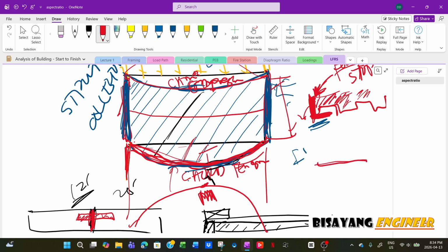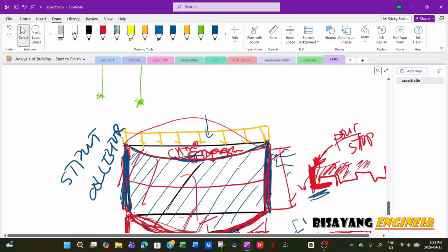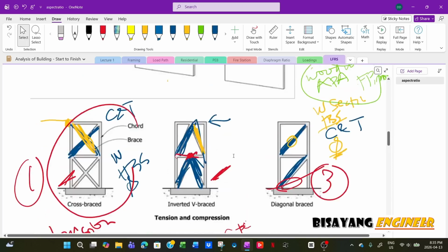So if you have a steel W section, and you are doing, say, a moment plate, like a splice plate right here at the top, to design the tension on the plate will be whatever is the moment divided by the depth. So the same concept as this diaphragm. Once you get the reaction, you will apply that to the shear wall. So the shear wall is like this one.